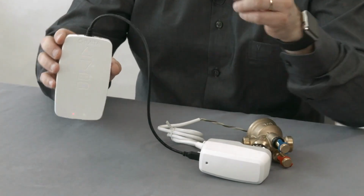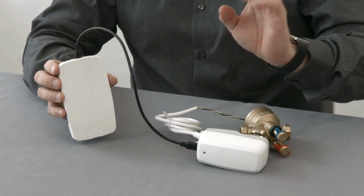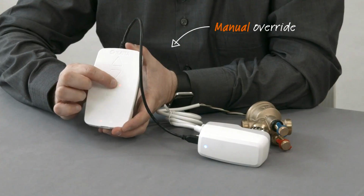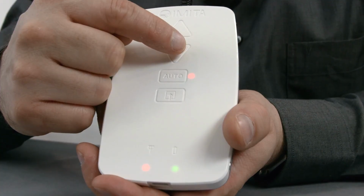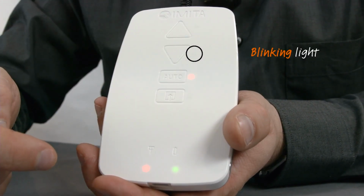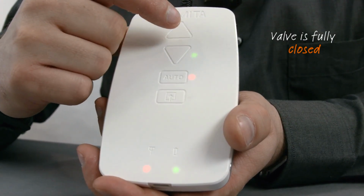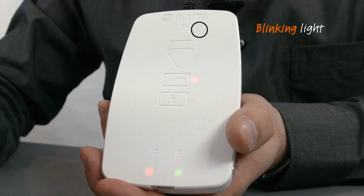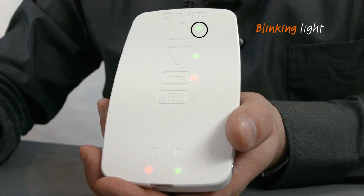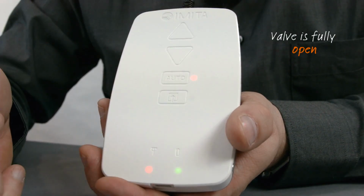For instance, if you want to measure the flow through the valve, you would need the valve to be fully opened, and the easy way to do that with the dongle is simply to press on this auto button here to switch to the manual mode as the red LED is indicating. I can see from the LED blinking there that the actuator is already in the fully down position, so I will request it to go up by pressing this up key. And by the simple press on this key, you can now see from the LED blinking that the actuator is progressing up. If I let it go throughout, it will stop when it's reaching the fully open position of the valve.